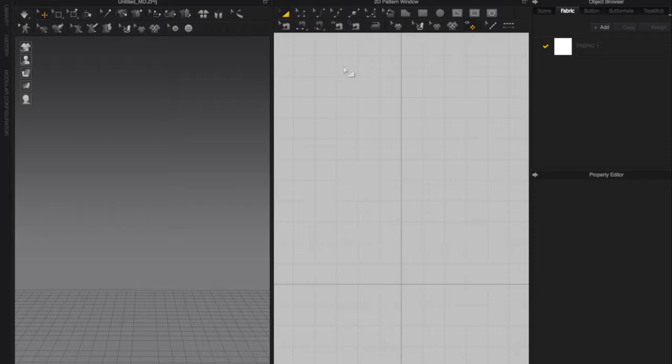This window on the right is our 2D view, where we will plot points to create the clothes, then simulated and draped onto our avatar. If you're familiar with costume construction or clothing making, this is basically where we're plotting points to make a flat pattern, just the way you would to then cut out a fabric. If you're familiar with Illustrator at all, this is very similar to creating vectors in their program.